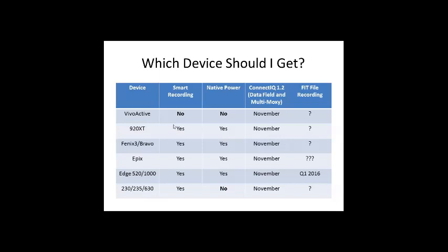The next question is also, can you do an actual pace or speed rather than an average? And this is an astoundingly complicated question for as simple as it sounds. The access that we get in ConnectIQ to the data is somewhat limited. We don't necessarily get access to the raw data of the watch, or the raw GPS data. So we get whatever you could have displayed in the native portion of the watch. On devices like the Vivoactive, the watch averages the pace all the time natively. It's about a 1 minute smoothing on the pace, so when we ask it for the pace in ConnectIQ, it's giving us that 1 minute smoothed pace.